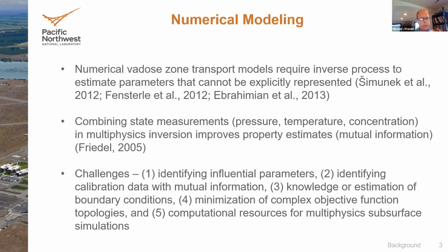So numerical vadose zone transport models require an inverse process to estimate parameters that cannot be explicitly represented. Combining the state measurements such as pressure head, temperature, and concentration in a multiphysics inversion is known to improve the property estimates given the presence of mutual information content. Some of the ongoing numerical modeling challenges that we come across include identifying influential parameters, identifying calibration data with mutual information, and the high performance computational resources necessary for multiphysics subsurface simulations.